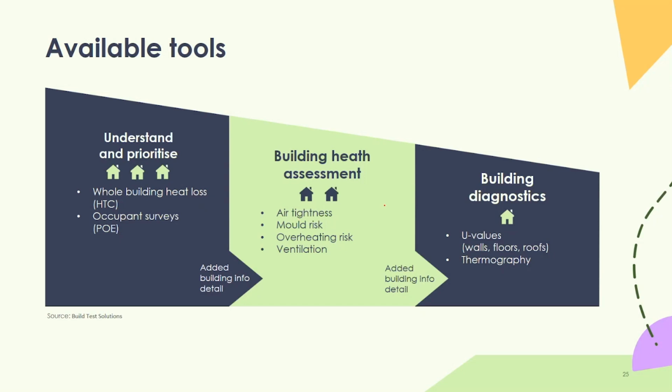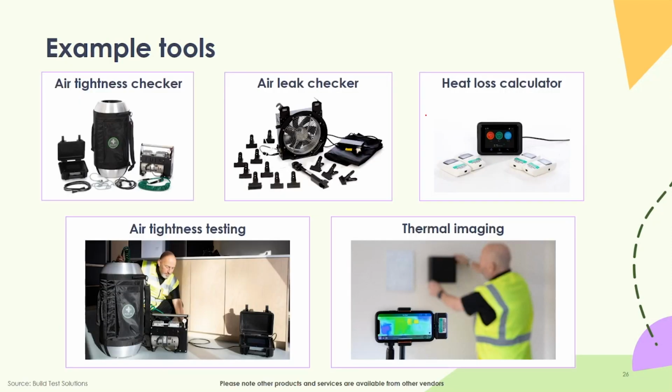And then from there, at your discretion really, you can drill down further if you did want to specifically understand heat loss rate through the walls, the floors, the roofs with U value measurement and perhaps some thermography. So definitely not advocating throw the kitchen sink at it, do measurements on every single property to the nth degree. It's more, do HTCs at large, which can be done with smart meter data, low cost sensors, and then drill down from there, basically.